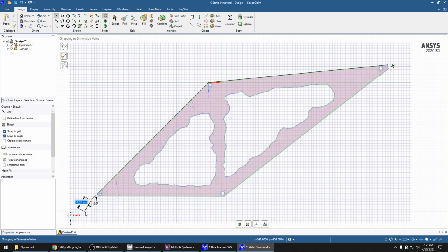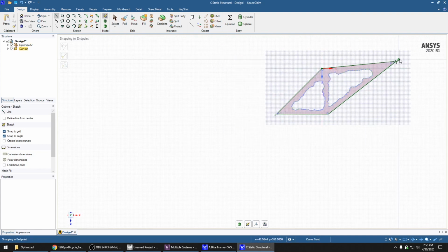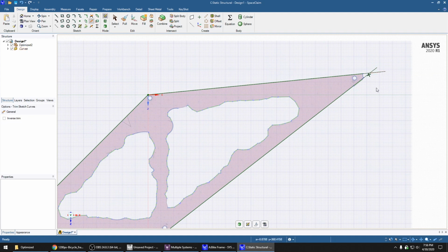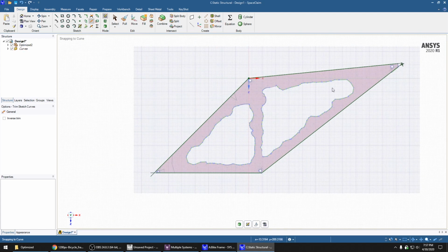This is why we imported a file, right? I'm gonna overshoot. I'm gonna press. You see, it's like hinged off of that. I'll press escape and repeat. Again, overshoot it, but snapping too. I can ignore this little extra piece here now, and I'm not sure this top line is gonna work actually. But so what I've done is I can either click here or press T for trim, and just trim off the excess pieces. Like so, 1, 2. Perfect.